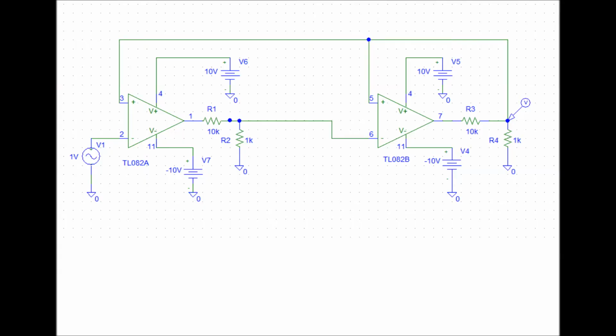After doing the experiment, we analyzed the circuit and realized that using a two-stage unity gain amplifier is better than a single stage because this circuit has a higher desensitizing factor which results in a higher input impedance and lower output impedance, which is required for a good buffered circuit.